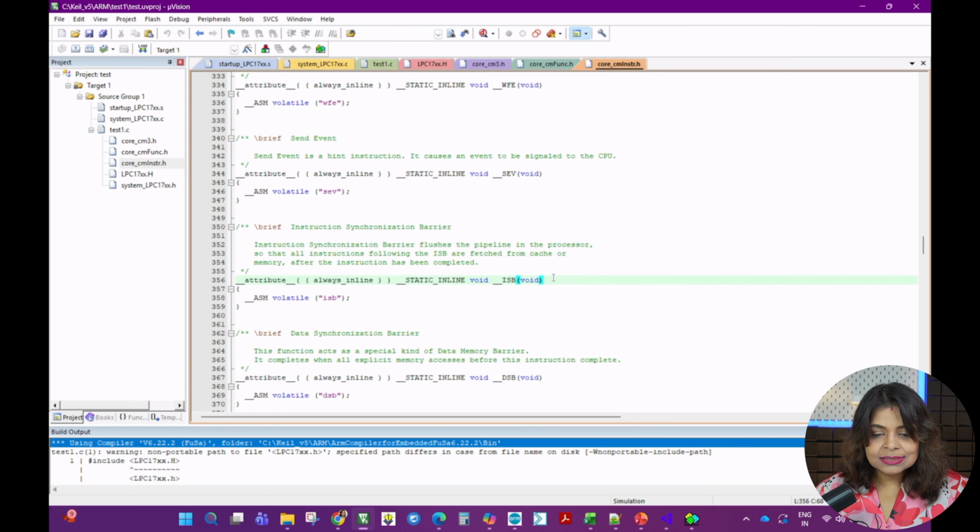That is the best, because when we write a C program, it's fine, but many users tend to write in C thinking it's a high level language, and C is very popular in the market, though it is embedded C or normal C. Everyone tends to write the program in C, but they never understand that a C program is just a high level language that has to be converted to low level opcodes, which is done by the tools. But we don't know whatever compiler you're using may add additional code to it.